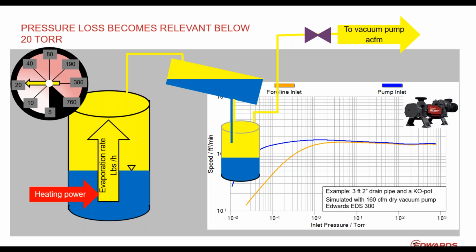So imagine the volume under vacuum, the yellow parts of this diagram is a dust cloud. It's a homogeneous dust cloud with little dust particles flying around. The point is, how do you get this dust cloud moving out of the system towards the vacuum pump? If the density of the dust cloud is relatively high, that's fine. It's no problem. The dust in the vapor state in your reactor would still feel the pull of your vacuum pump when the density is high.